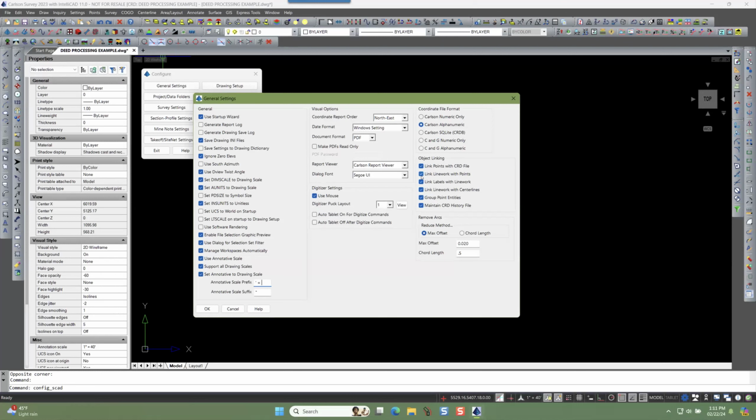And if it was not on, if you moved the point in the drawing, it did not update the CRD file, in which case you would move things around the drawing and you come back in, you later go to print out or stake out your points or do something, or if you redraw the points from the coordinate file, they would come in at a different location back in the original location if they had not been updated. So you had to sort of keep track of that all by yourself, and you turn this linking on, which would make sure that they get linked together.